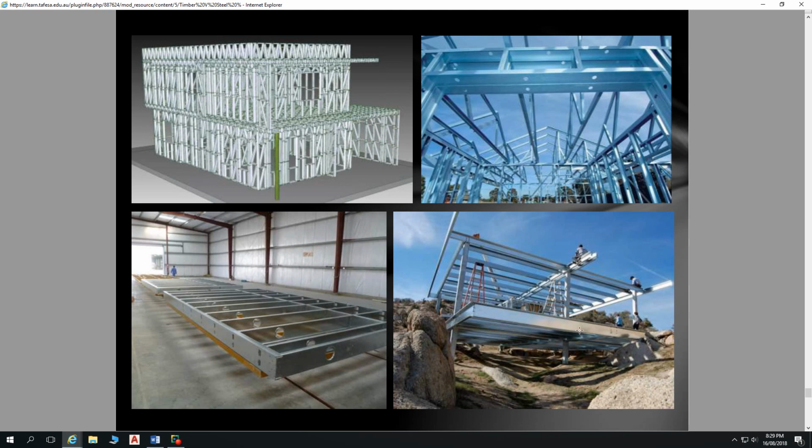That is probably one of the main reasons why people are happy to spend money on these types of frames. Why they're happy to spend that $5,000 a day to have a crane on site, and happy to spend, I can't remember how much per linear meter those beams cost, but they're expensive, and the design, etc. It's for that flexibility of having large windows without any bracing.